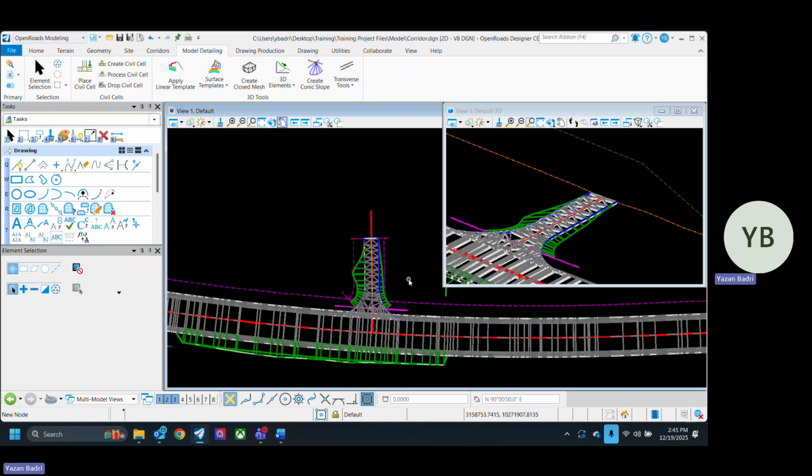But then how do you merge all of those together? Good question. You don't need to, but if you want to see them all in one place, create a model container for the file. You reference all of them and then they will all show up in one place. Right, because we want to look at all the contours together. Yeah, if you want to create proposed contours for the whole project, you can just reference all of the different pieces, select all the corridors, and it creates a proposed mesh for you.